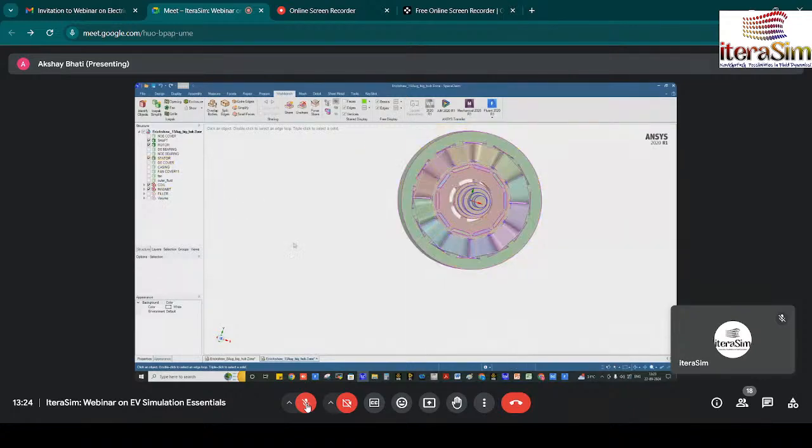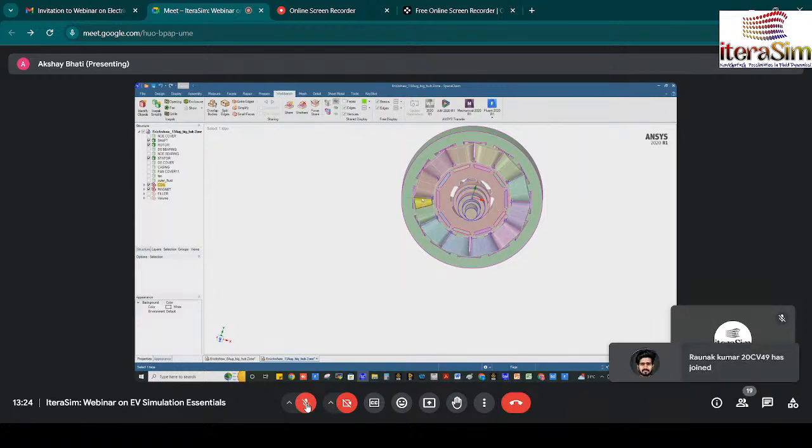That is the stator. Okay, so here you can see the assembly of shaft and rotor. In the rotor magnets are there, the rotor will rotate, so it will rotate the shaft, and that is the end winding, the electrical winding. And that is the stator part, it will be fixed. Okay, so based on the electromagnetic effect there is the magnet, and because of that copper winding there is EMF generation that would rotate the shaft continuously.